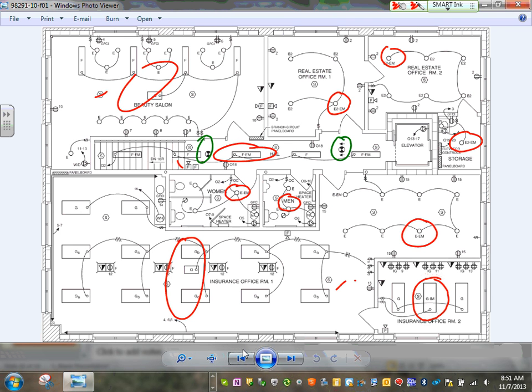Only you have to maintain 1 foot candle, enough for Karen to get up and see her way through to the door. Okay? And again, I'll walk you guys through this one. But for the time being, I want you to pay attention to the emergency light and the exit signs. For our project, Brian, these will be battery operated, because we do have a generator, but our generator is not an emergency generator. It's a backup generator, just to back up the power.